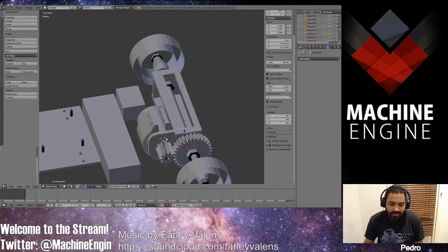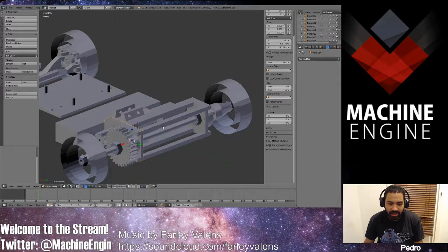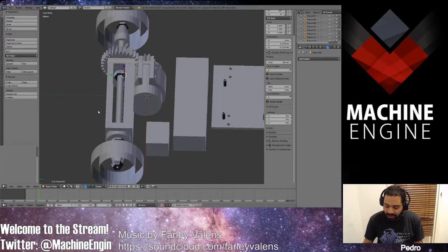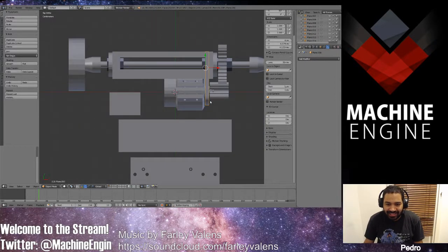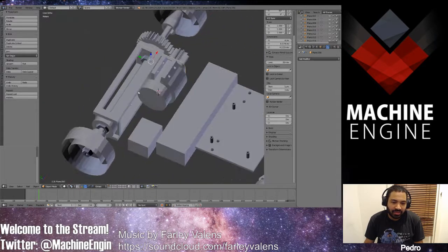Gonna have to do some tweaking on the design later on, because when it's 3D printed, some parts are gonna be weird. For example, this one here, I'm gonna print it on this side. That's because this side is on the floor, and you reduce the overhanging struts that way. And also the thing with 3D printing is these parts have to be a perfect circle.